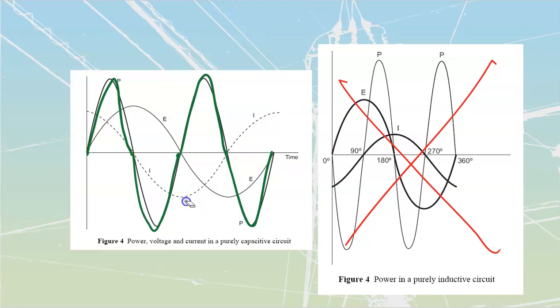What you see coming out of this thing is a frequency waveform, same as the inductive one, that is going to be double the frequency of my base. It's also going to be doing that same thing where it's taking power and then dumping it back in, taking power and dumping it back in. Generally speaking, this is seen as being a waste of time, to take something out and put it back in. We used that bank deposit analogy in the previous video. It is not something we desire to see.